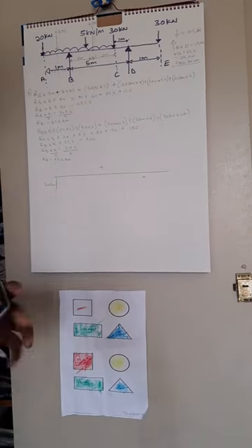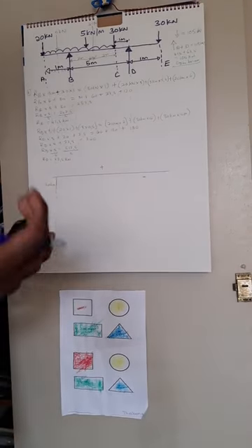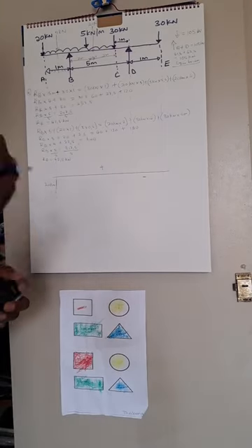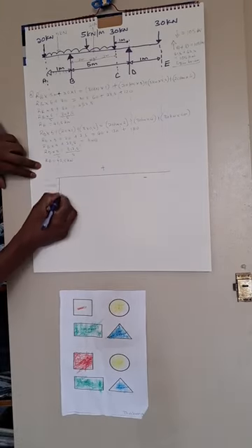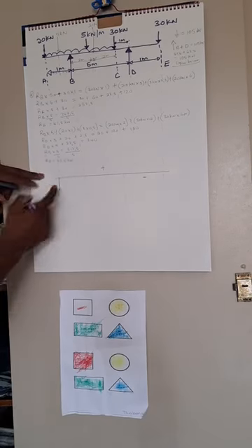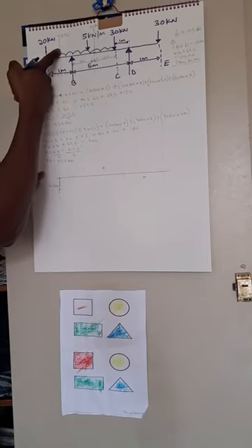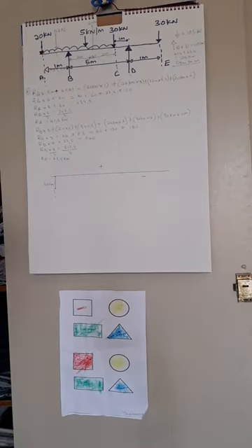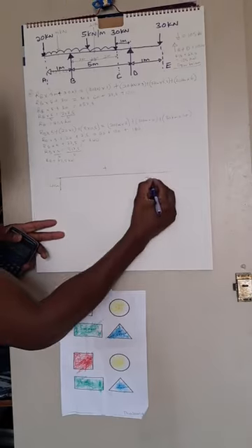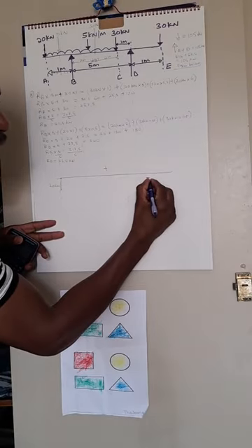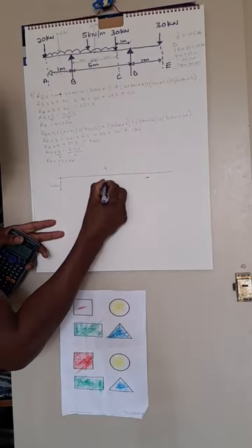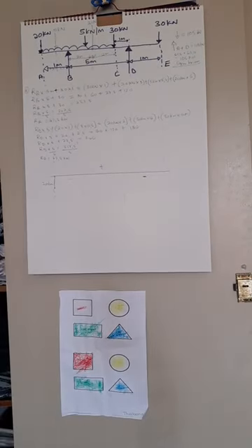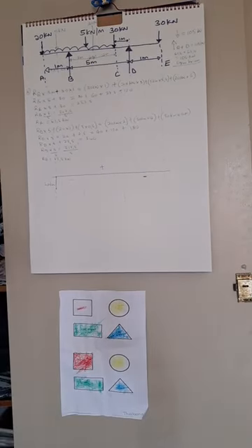Remember, in N4, we don't draw to scale, we draw analytically. In other words, we are drawing a thinking. So if I move a smaller distance from this point to a point like this, which I say is 20 kilonewtons, but between A and B, we have a UDL of 5 kilonewtons. Don't forget, already here I said any force that is going to fall on this column is a negative force. So any force that is falling here is already a negative force. I don't know why my pen is running out. Let me get another pen.